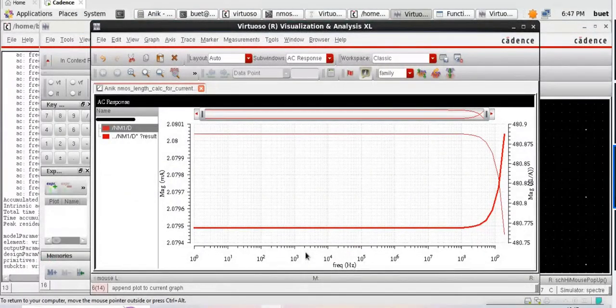Let us reiterate these things, because what is the intent? Like I told yesterday, the output resistance of a current source should be very, very large. Ideally speaking, it should be infinite. The reason I have already posted yesterday. Now the same MOSFET for which you are calculating the output resistance, this MOSFET only you are going to use in the current mirror or current source design. So by that notion, the output resistance of this MOSFET also should be very, very large.